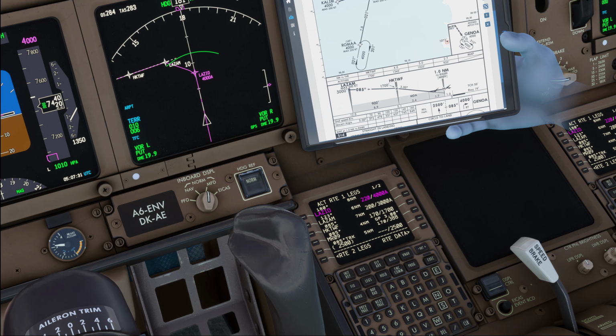Now, whenever technically available, the autopilot should be used during the approach to give autopilot alerts and mode fail indications, more accurate course and glide path tracking, and lower RNP limits. However, it is not allowed to fly an instrument approach using VNAV when your altimeter is referenced to QFE rather than QNH.